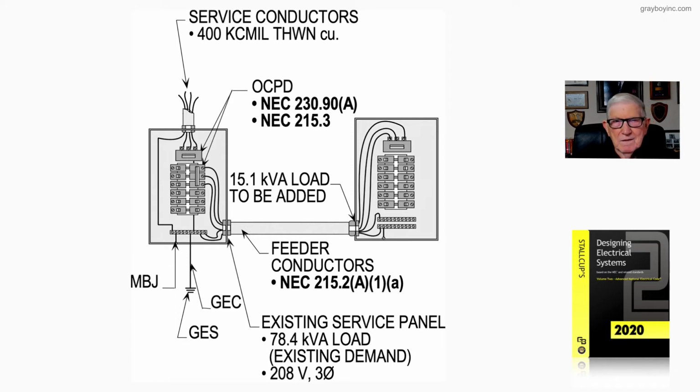And then the exception basically states if the feeder or service has any renewable energy systems, then they should not be figured in the calculation, because there's no way to tell how to get an accurate reading on just exactly what is used when you have an alternate power source tied in with the utility, or just tied into your panel board. That may be a wind generator, it may be a PV system, it may be a battery system of some sort, or a generator. So this is basically what the exception is talking about.